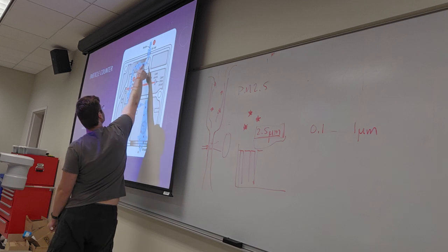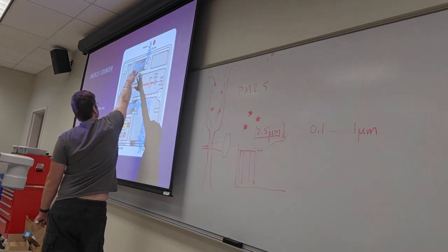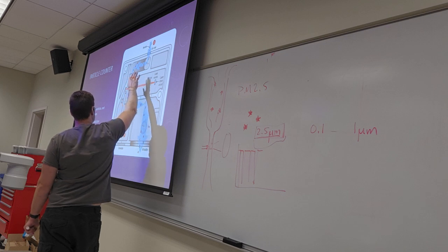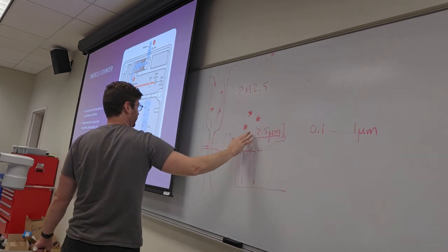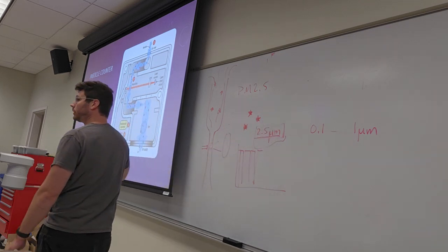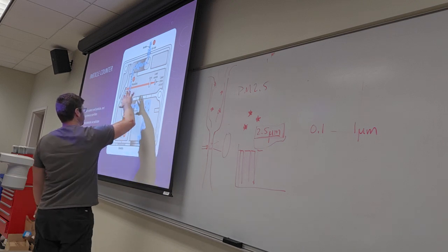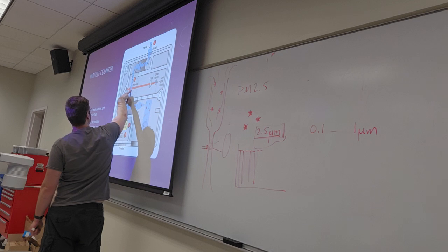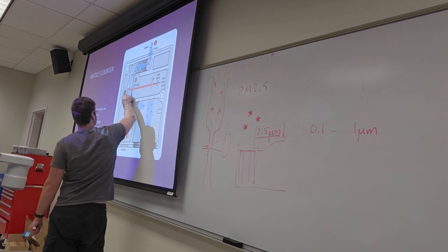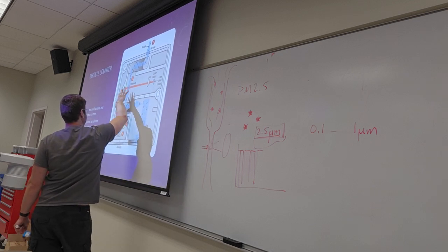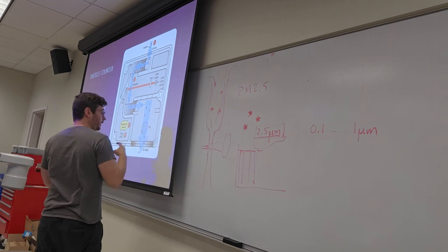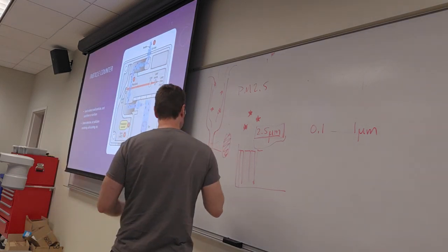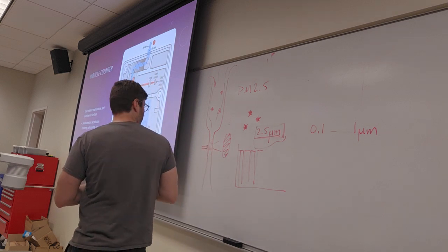So they have an air inlet, a sampling pump. Sometimes they have filters to make sure that you're only sampling approximately this range, or to kick out things greater or lesser than it. Again, reduce false positives. You have a photodiode or a laser that puts a spotlight on that little dust, literally magnified, suspended in the air, and then this spot will darken as something passes over it.